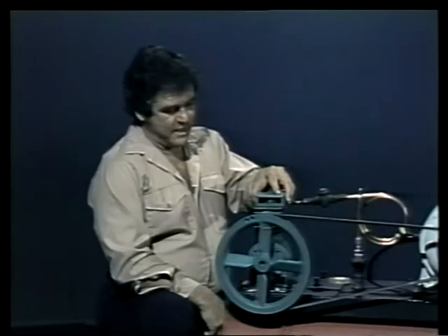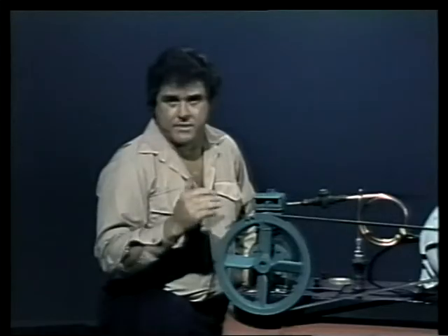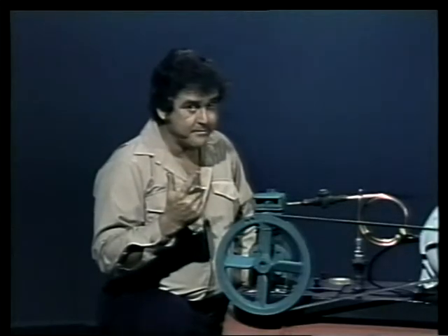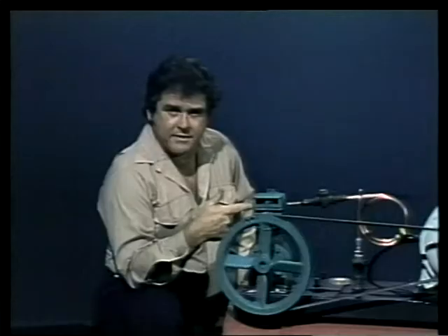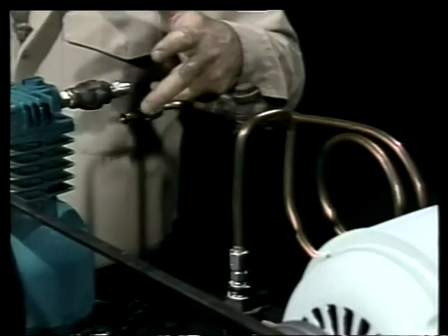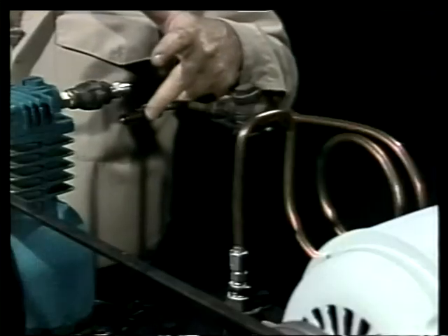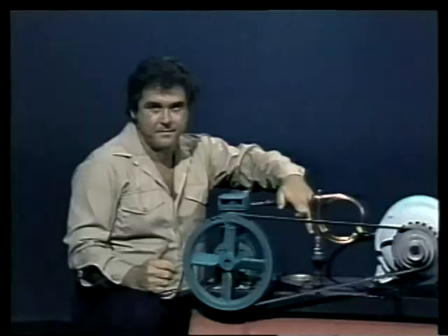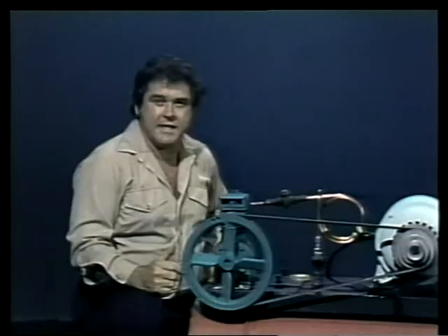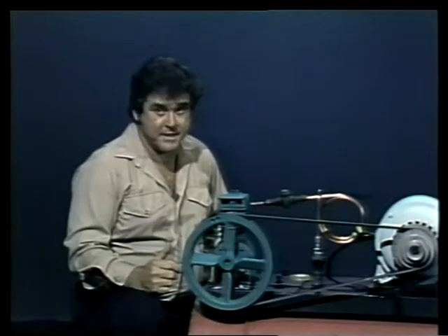Now, there are several types of reciprocating compressors. They're categorized by the number of cylinders, number of stages, according to whether they're single-acting or double-acting, and their layout. This compressor is a single-cylinder, single-stage, single-acting, vertical reciprocating compressor. Now, let's see what that means. A pipe connects at the discharge point directly to the receiver. Now, that's the case on any kind of single-stage reciprocating compressor.